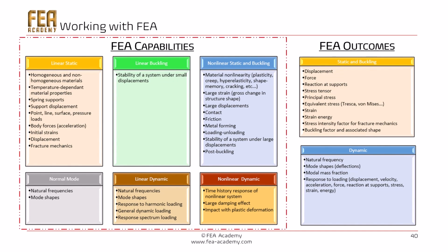So let's start with the FEA capabilities. You have different scenarios: the linear static analysis, the linear buckling, the non-linear static and buckling, the normal mode, the linear dynamic, the non-linear dynamic. Here are the different solutions that you can submit on a simulation. And you can see for those solutions, you have access to different capabilities. And you see, it's a wide range of capabilities. So it's like finite element analysis is unlimited.